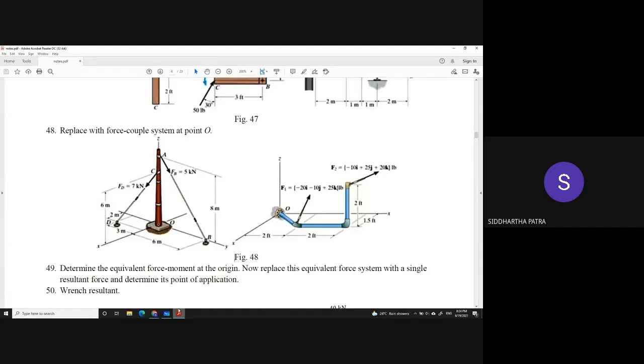And if we have a situation where the resultant force and resultant moment are orthogonal to one another, for example a planar force system or a parallel force system, or any general situation where that is true, then we can think of M parallel being equal to 0.